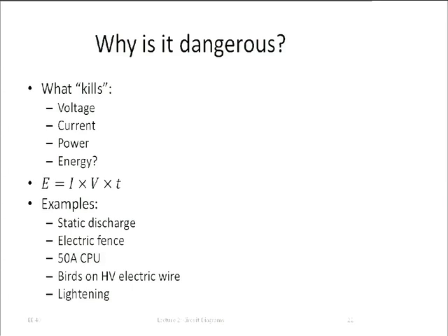Okay. An electric fence is for cows and so on. How much voltage do they use? I once designed one. It was like 20,000 or so. Okay. But again, what you do there is you load that voltage on an inductor, and we'll look at inductors later, and you make sure that the energy that inductor can store is very, very small, and therefore the energy is smaller than what is required to really hurt a person or a cow, for that matter.